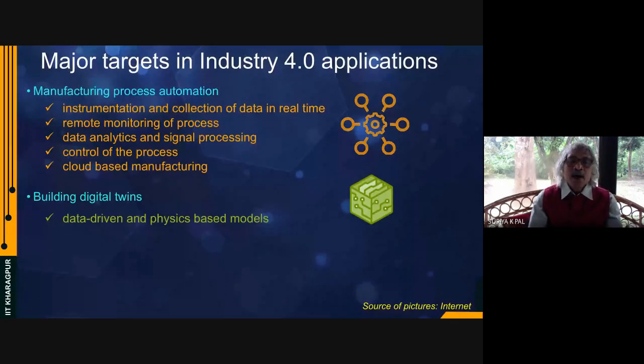It is nothing but capturing data by using different sensors from the machine and portraying the performance of the machine by collectively acquiring information from the different components. One could be the heart, which is the motor of the machine. Then the feed movement, that is the table movement, tool movement, spindle movement, the hydraulic oil quality, temperature, whether there is any leakage, vibration. All this data can be harnessed from different locations of the machine, and then you can analyze. That is called the digital twin.